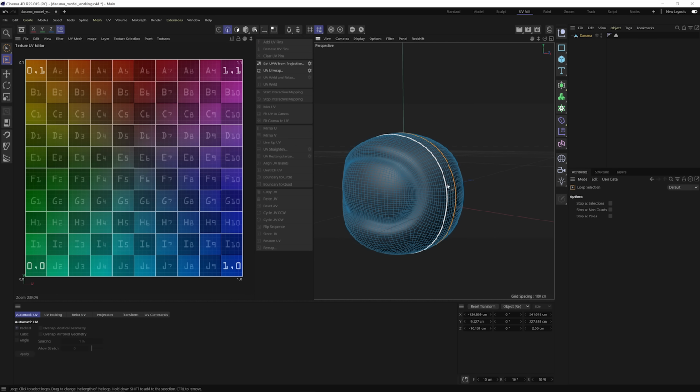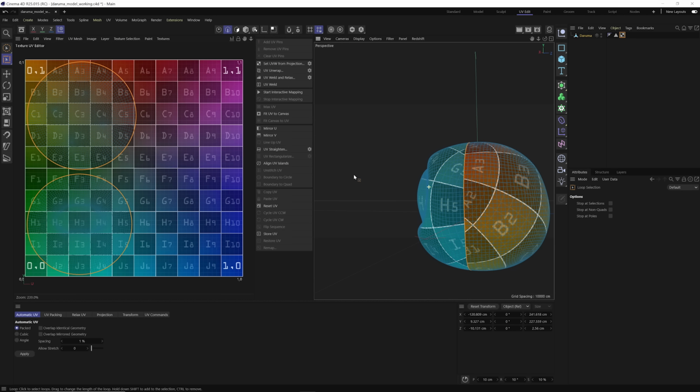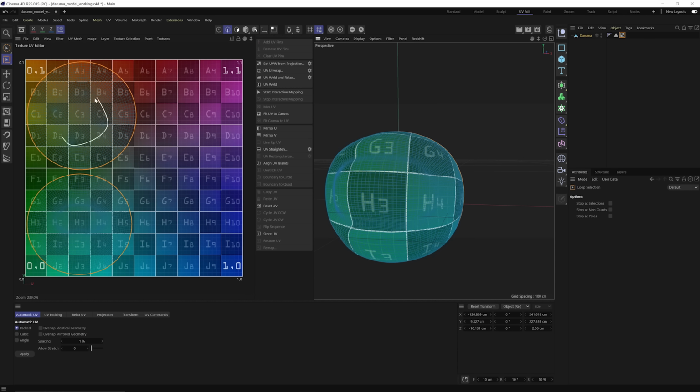up, right? So once you have that seam defined, I'm going to go to UV unwrap and you're going to see, voila, we have a new UV map here. You can see we have 2 islands of polygons versus 6 as we did before.